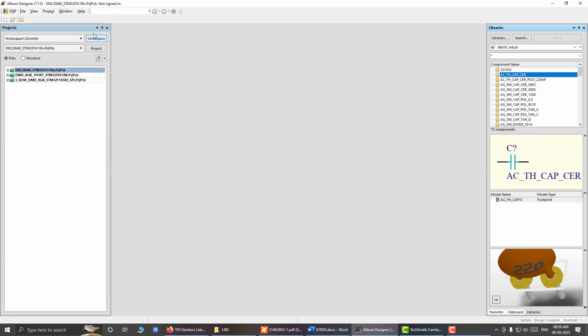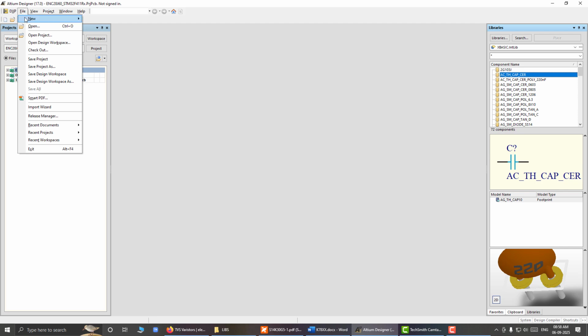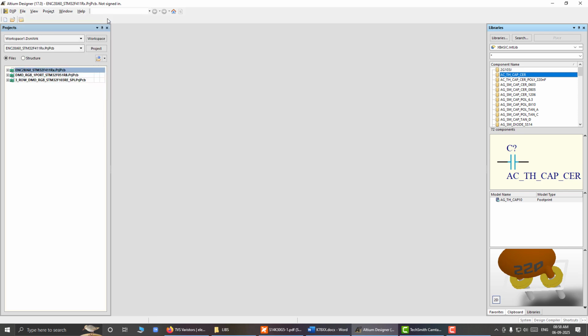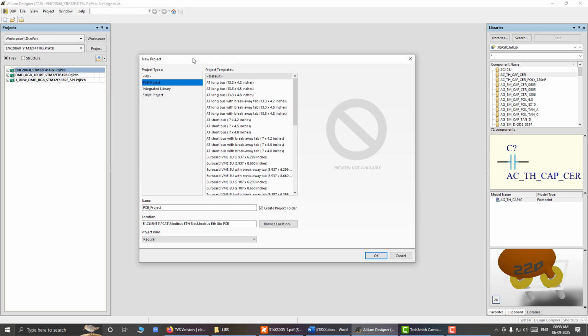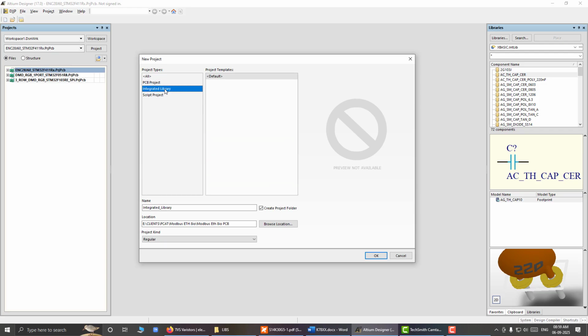So let us begin. Go to the file menu, click new and select project. In the previous video we selected a PCB project, and in this video we have to select an integrated library project, choose a name for your library and the location, and hit OK.